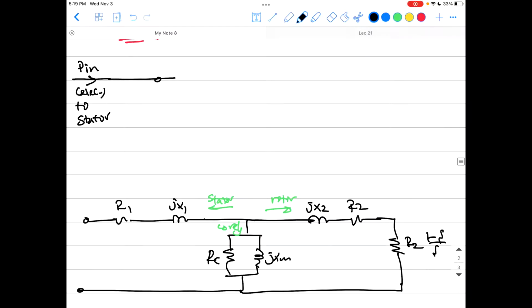So back to the power flow. The input power comes from here. So this input power is the power going here, P input to the stator, okay? And we start losing. Like we said, all the resistances in the equivalent circuit represent power loss. That's how things go, guys. So R1 is the first power loss you will encounter just entering this equivalent circuit. The power goes to the stator winding and you start losing some power as copper losses on this winding. Whatever current moves in a winding, you have losses because this winding has a resistance.